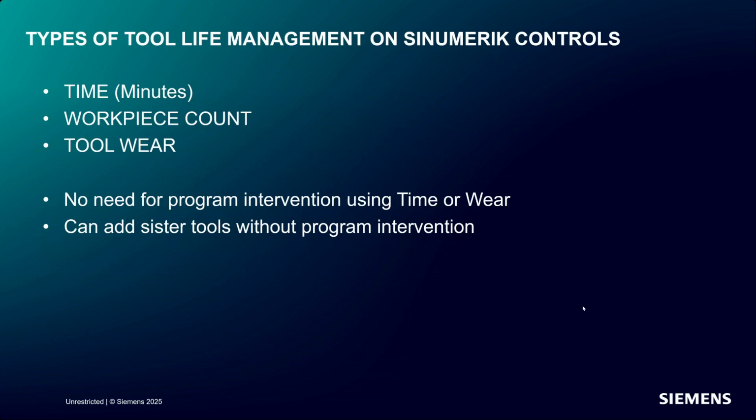What I really love is that if we use something like time or wear, we don't have to have any program intervention. There's no M codes that I've got to figure out, no tribal knowledge that very few people know about. I don't have to do anything to my program to implement tool life management or sister tools.